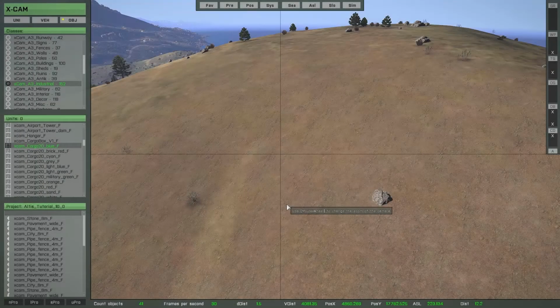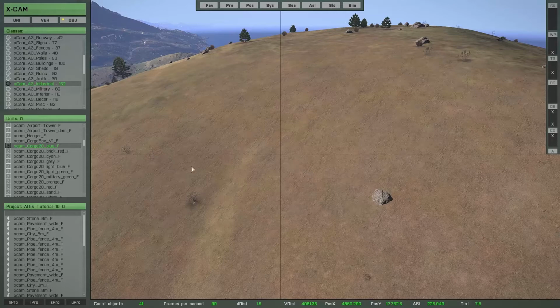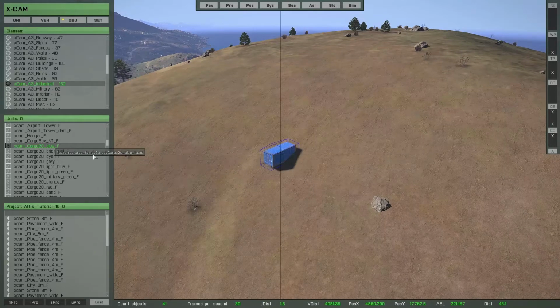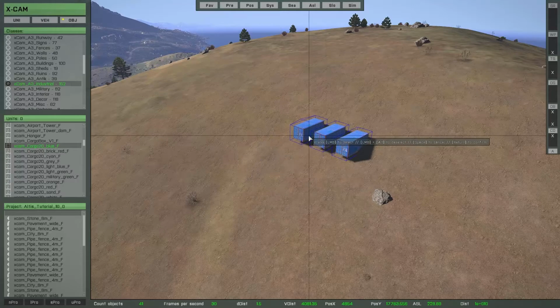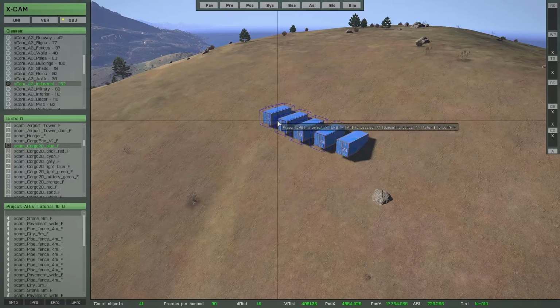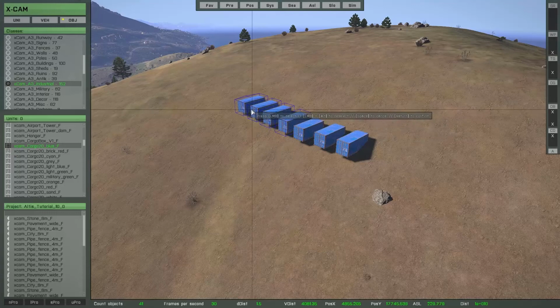It's also possible to switch the slope function on and off by pressing a key, and that's really useful if you work with a single brush, for example. So first start the single brush by pressing B, and now if you copy some objects, that's the result if you work with the normal mode.